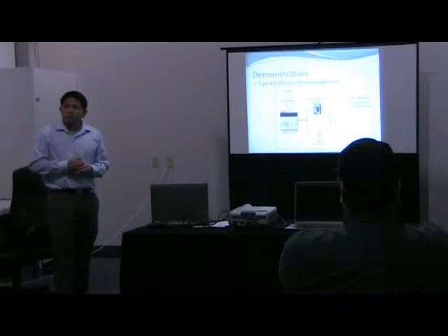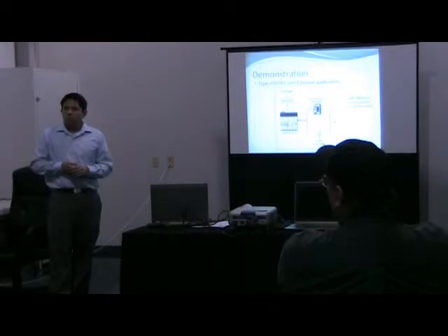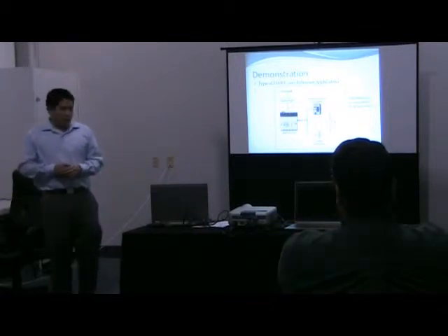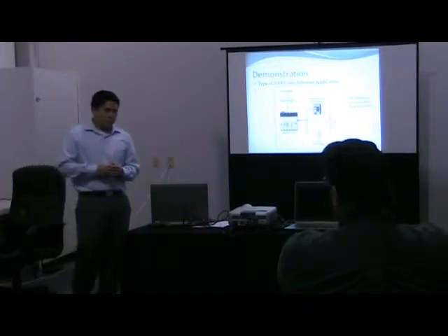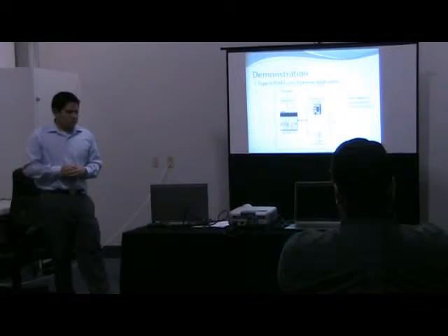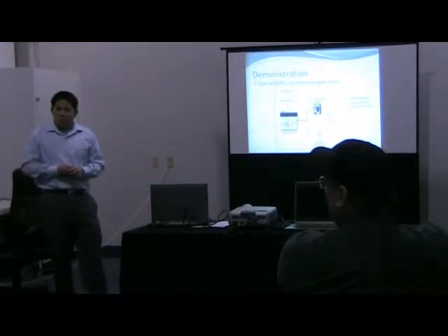If it's like a resistor on the HART modem, there's less of a chance, but if it's a connection that has the capability of internally dying at the modem, then you lose that loop a lot easier. Right, yeah. Another concern: if it's not a greenfield site and it's an existing installation, why are you doing that? Is there a concern related to moving wires to plug it in?